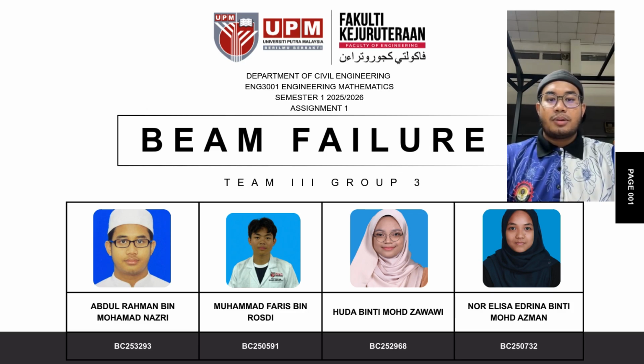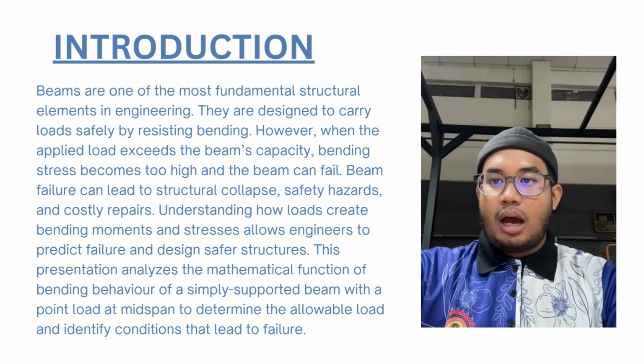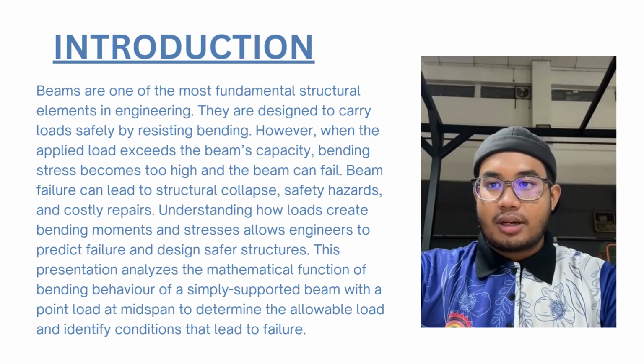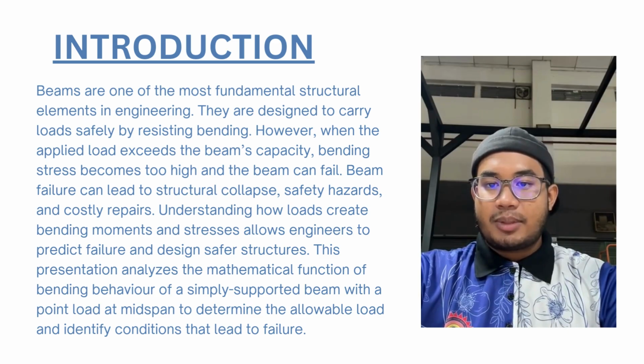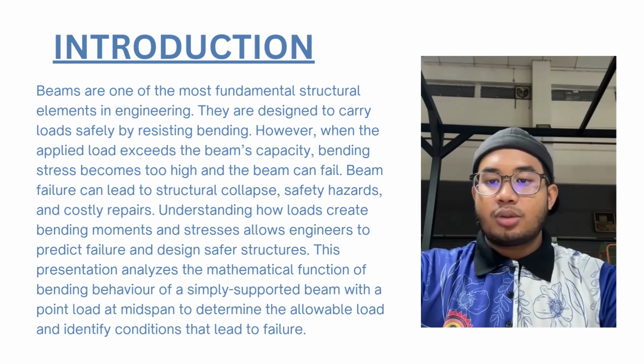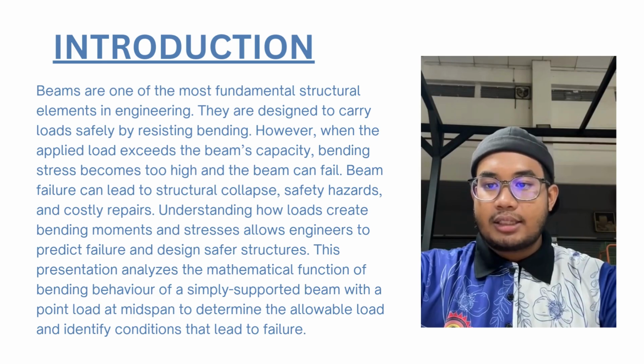We are going to be presenting our Assignment 1, Mathematical Function in Beam Failure. Beams are one of the most fundamental structural elements in engineering. They are designed to carry load safely by resisting bending. In this presentation, we will analyze the mathematical function of bending behavior of a simply supported beam with a point load at midspan to determine the allowable load and identify conditions that lead to failure.